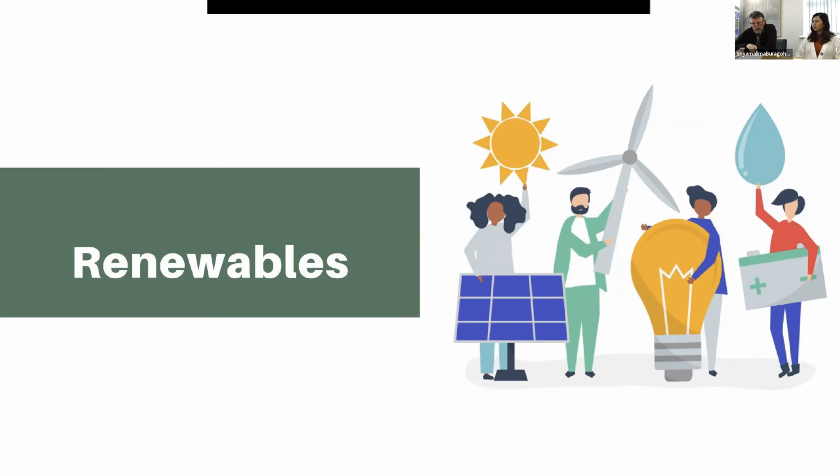They have a coefficient of performance representing the amount of electricity or energy that needs to be put in to the energy that's taken out of it. And again, that figure is growing with improvements in technology, and it's up to 4.5, 5 coefficient of performance, which means 4 or 5 times heat is generated from the amount of energy that goes into it.